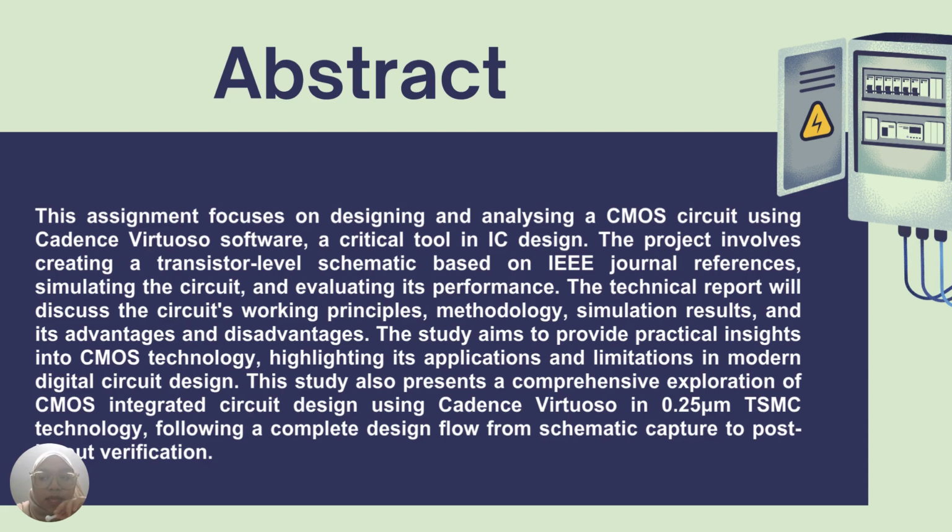And the last one is analysis, where we discuss the working principles, results and trade-offs of the design. This study provides practical insight into CMOS technology, showcasing its application and limitation in modern digital circuits. We also demonstrate a full design flow from schematic capture to post-layout verification, ensuring manufacturability in 0.25 micrometer TSMC technology.